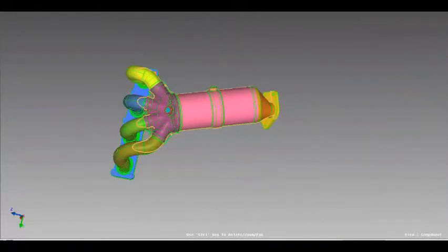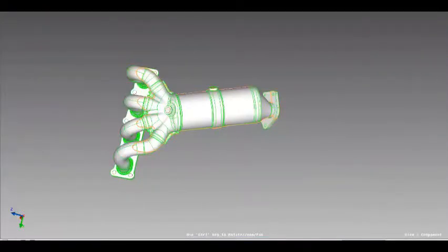So for that I'm going to use the wet surface isolation method, which is in the CAD tool. The minimal inputs we give are that I need to select all my surfaces, and the user has to specify the resolution and tolerance for the cavity generation. It is based on the size and the complexity of the CAD. Right now I'm going with 10 as my resolution, and just say find inner cavity.